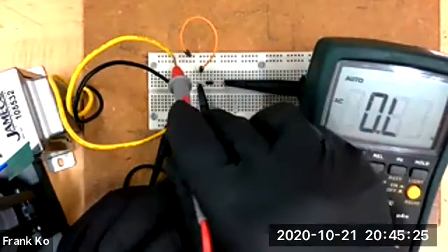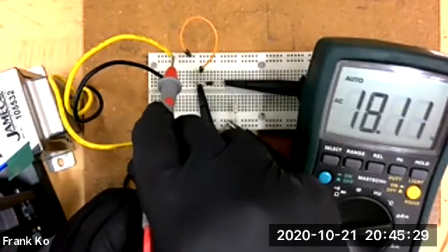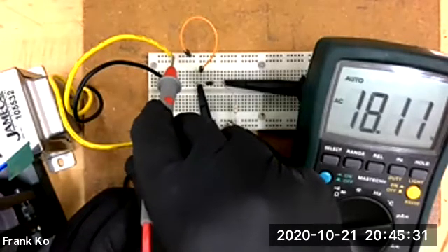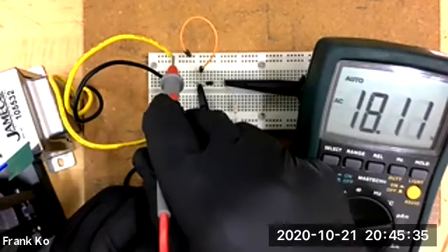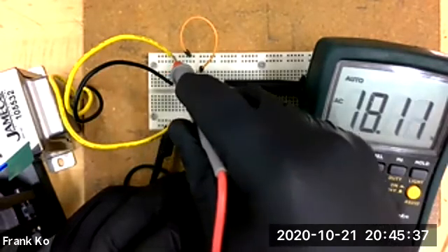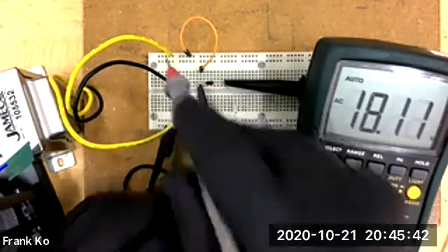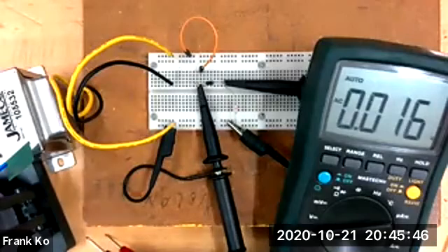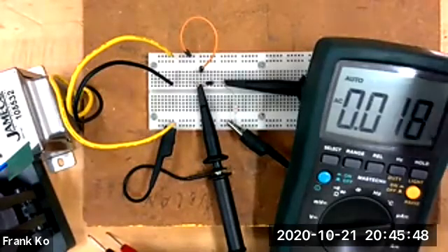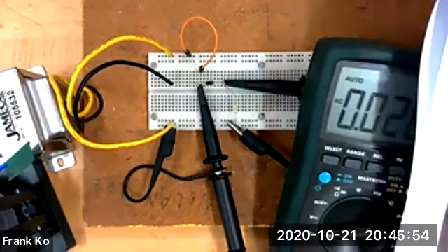There's my RMS for my board. Yours comes out to about what, 19 volts RMS? 18.8. You had 18 point something RMS? Okay. And your oscope, on the other hand, measures waveforms, measures peaks. So that's the reason why they're different.